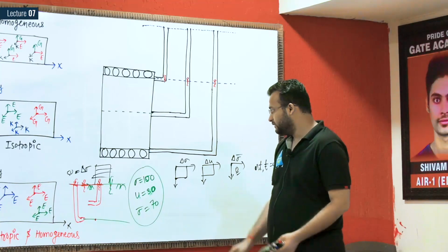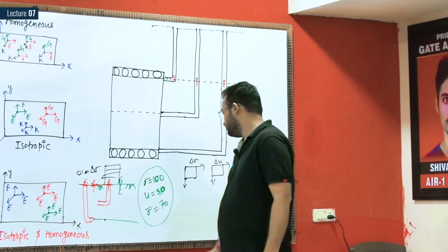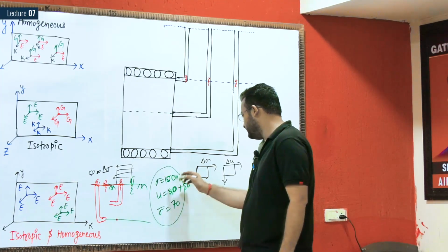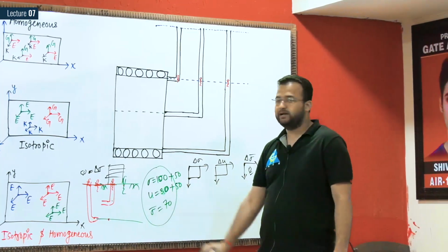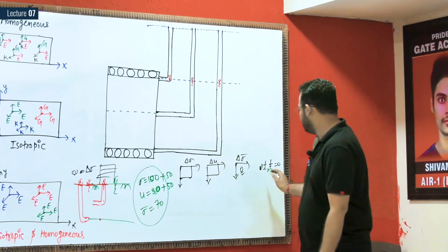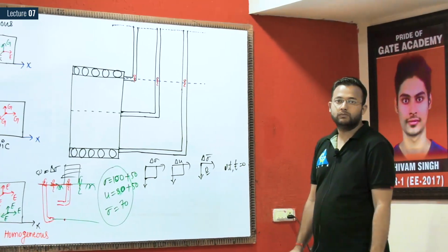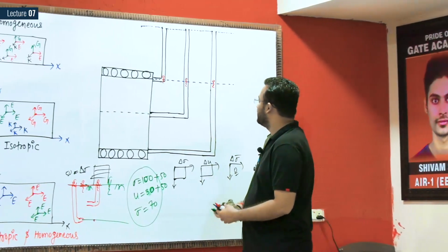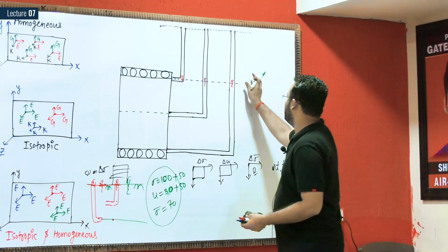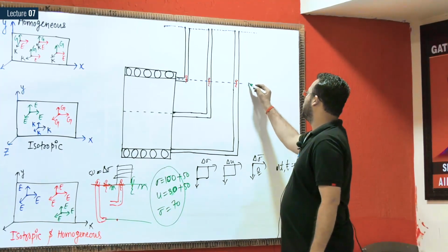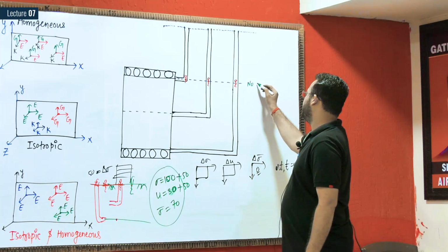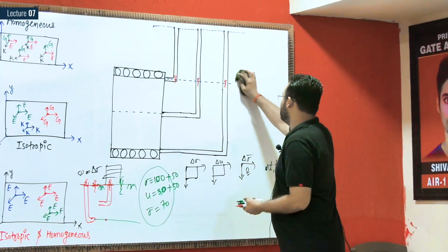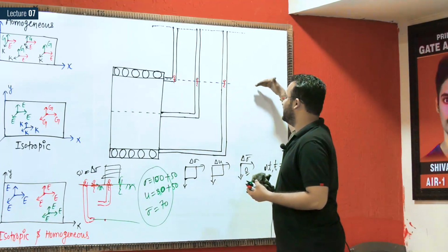So immediately the complete value of delta sigma will be taken by pore water pressure. Means this 50 additionally we have applied. Complete value of 50 is taken by water. Soil solids at the time will not take any value. If soil solid is not taking any value, suddenly what will happen? This is the condition when no pressure, no delta sigma bar has been applied. I think it is clear to you. At this level, this is our initial level.